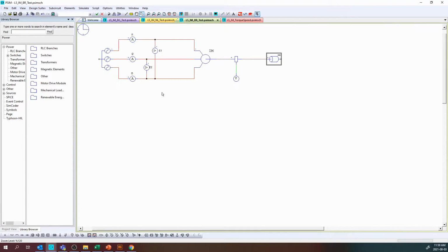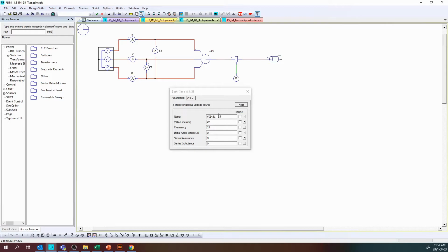You can't just put the nominal value in the supply voltage, because if you do that, you will basically burn the motor, or if the motor has some electrical protection, you're just going to trip it. That's not what we want.